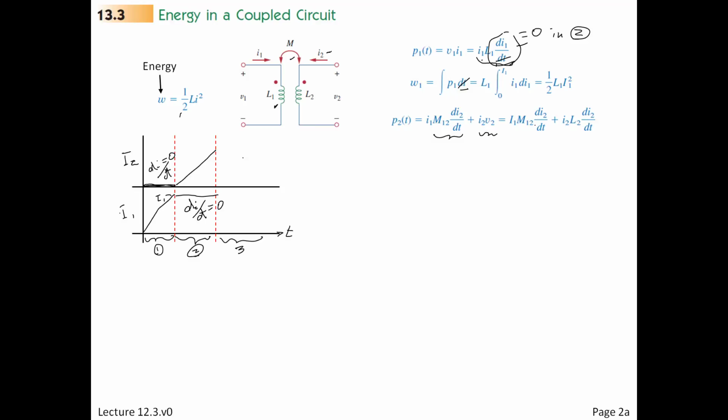Here's just what's happening on the number 2 side all by itself. So here is that expanded now. We put in di2. We got this mutual coupling from the number 2 side back to the number 1 side. And we're substituting now in for the voltage on the second side. And this we are going to want to find the work for, so we integrate all of that. And that means we now have what? M12, the mutual coupling, times the current on the number 1 side. But this is steady, not time changing, so it's a constant value there at I1. All right, and we're going to be integrating I2 from 0 to I2.